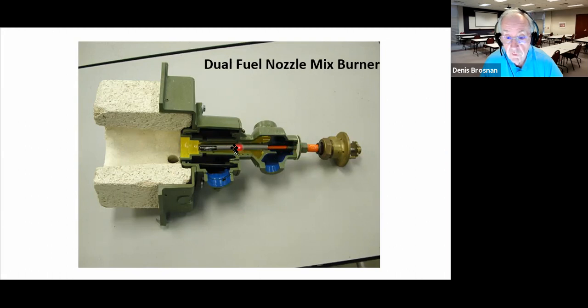It uses the heat from this housing to vaporize, and then some air is injected into that oil chamber in order to push that vaporized oil into the burner. So you can operate either with air combustion and fuel, natural gas, or air combustion and oil in this burner.